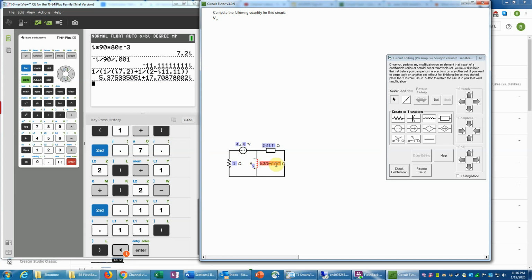And notice also that's in red because, again, that's not appropriate for an inductor. An inductor should have a positive imaginary impedance, and this is a fully complex number. Therefore, we have to change that. And so I'm going to click on the general impedance symbol and change that element to that. And then the red lettering goes away, which means that that's now acceptable.